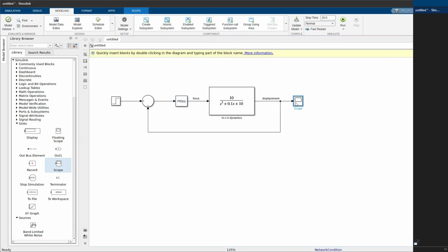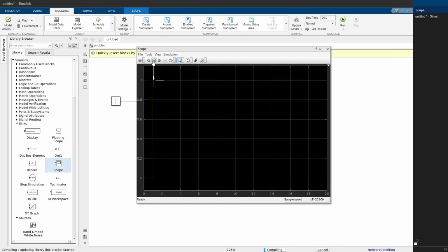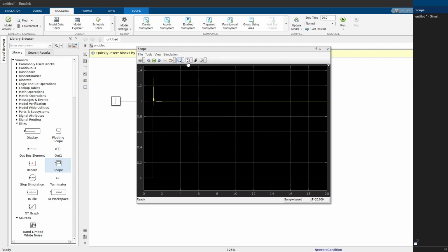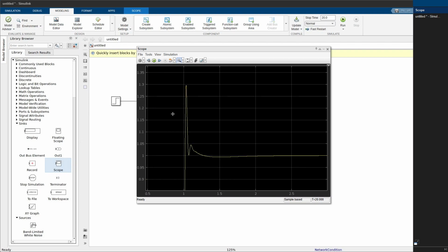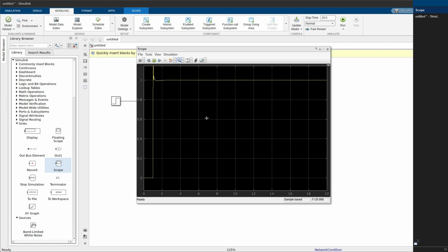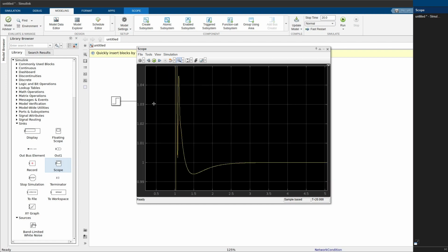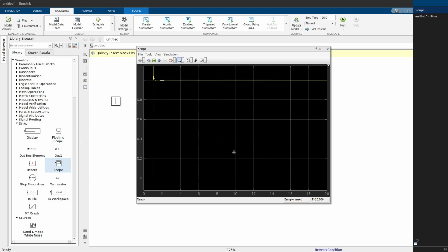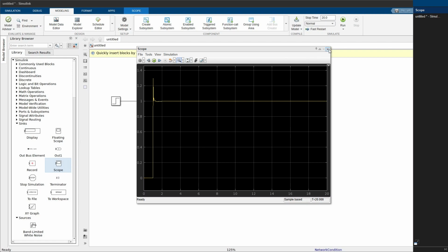All right, so let's say you have these basic gains that you have designed, and you say okay, and then you can double click your scope, run this, and get a response like we see on the screen as an example. Here, let's say we have about 30% overshoot, and maybe that's too much. We want to improve that and reduce it, and we have a settling time of approximately maybe about 1.5 seconds or a little less, and maybe that's something we also want to improve. So all right, we want to make this better. How do we do that?